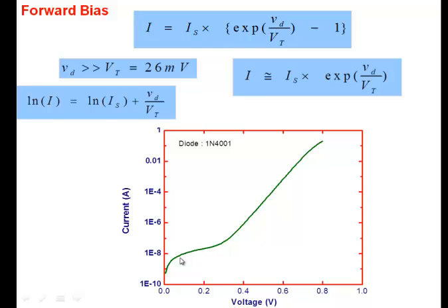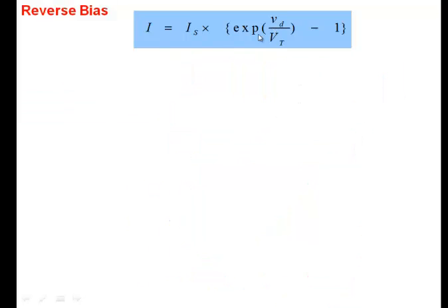It breaks down here. The current in a PN junction is limited more by leakage. There are various sources of leakage, so it's not that exponential here. Similarly, at very high currents it will deviate from the straight line and start leveling off, and that happens because of other resistances in the PN junction diode. In between, you have this nice exponential region, which on a semi-log axis shows up as a straight line. But at lower currents and at higher currents, the model will deviate from this exponential.